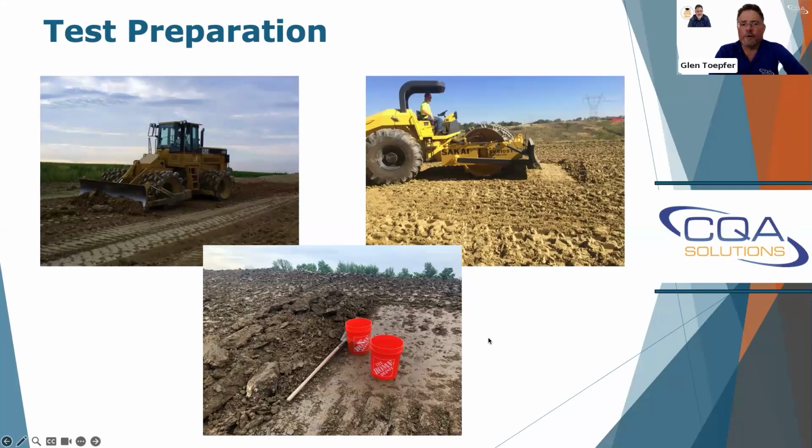There's different methods that people will have the test area cut, different compactors here with blades. This one was cut by a dozer. I've used foxhole shovels before, flat bladed shovels. The best thing that seems to produce the best results to me is a dozer. Their blades were made for cutting and grading. Compactor blades weren't. And a lot of times, compactor blades will tear.